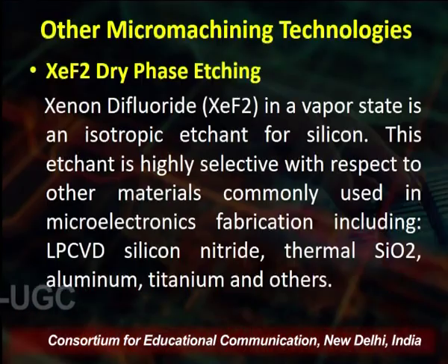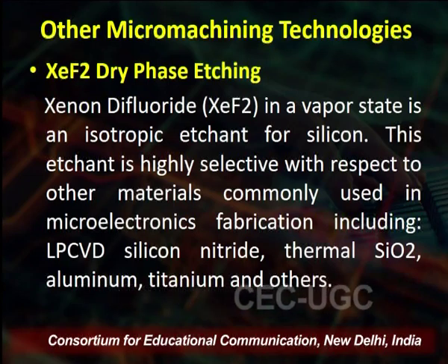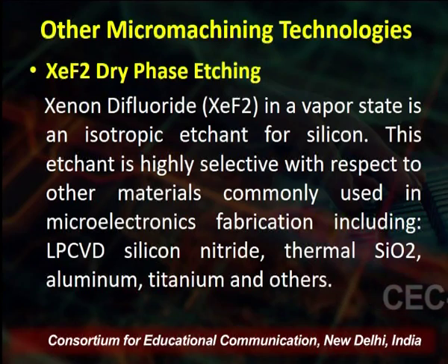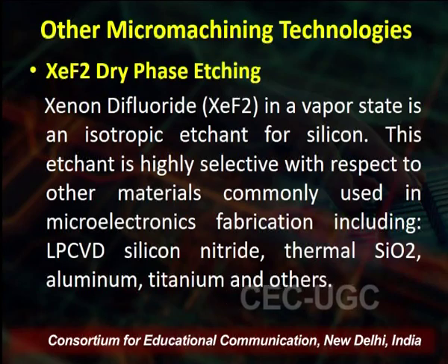Other micromachining techniques, in addition to bulk micromachining, surface micromachining, and high aspect ratio micromachining technologies, there are a number of other techniques used to fabricate MEMS devices. Now we have the XeF2 etching. Xenon difluoride, that is XeF2, in a vapor state is an isotropic etchant for silicon.